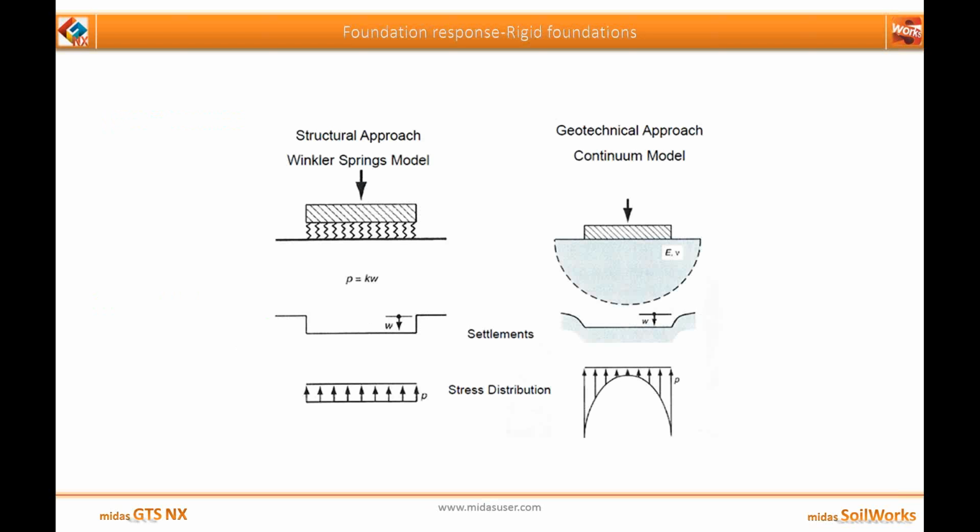Whenever we go for a rigid foundation in the structural approach, the stress distribution always comes as uniform from below, and the settlement is also considered as uniform. When compared to the real ground situation which we obtain in the continuum model, the stress distribution is very much different from what we actually have in our structural model.